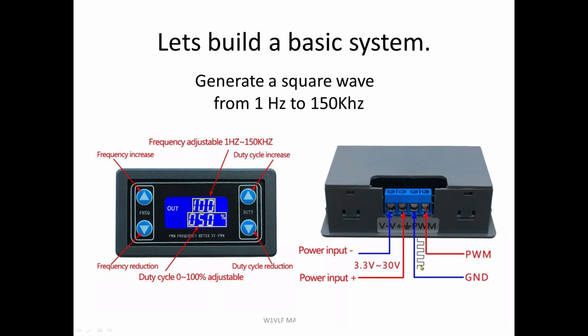So now what do you have? You have the baseline, 0 volts, then you have a plus voltage for a period, then 0 volts, a plus voltage, 0 volts, a plus voltage, and this is happening at your choice of frequency. I happen to use, I think, 16, 17 kilohertz because I'm using an SDR for detection, and I don't like going down below 10 kilohertz.